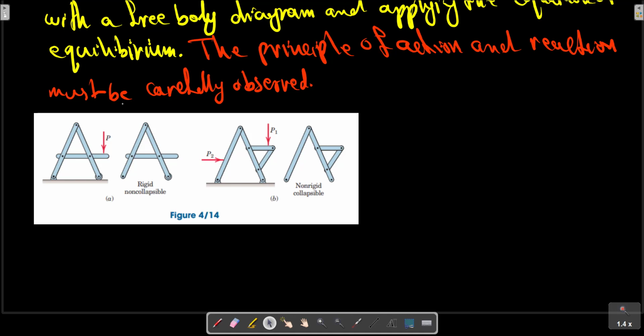If the structure is not a rigid unit by itself but depends on its external supports for rigidity, as illustrated in part B here, then the calculation of external support reactions cannot be complete until the structure is dismembered and the individual parts are analyzed. Force representation and free body diagrams in the members of a machine.